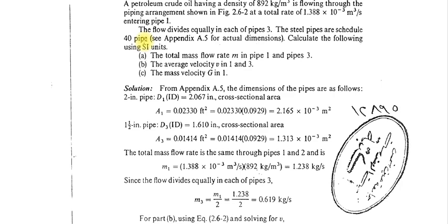So what are the important parameters for a given pipeline? There is the diameter of the pipe. When you define a diameter of pipe, it might be the internal diameter, the outer diameter, or the nominal diameter, that is the average of the internal and outer diameter. Generally a pipe is defined by a nominal diameter. And then the thickness of the pipe. If you want to use a pipe for higher pressure, you need a thick pipe. If you want to use a pipe for lower pressure, then you need a thin pipe. The thickness might not be much for a lower pressure pipe.